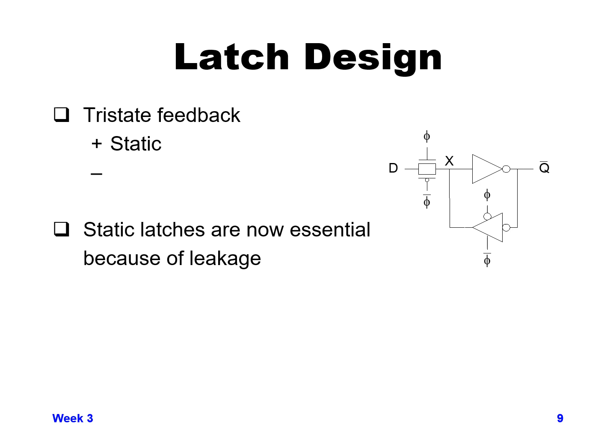Previously we said it was dynamic, where we're relying on a charge being held dynamically. If you take too long between storing a value in a latch and using it, and expect that value to just be held there, eventually parasitic current, noise, and other things are going to cause that X value to degrade over time.